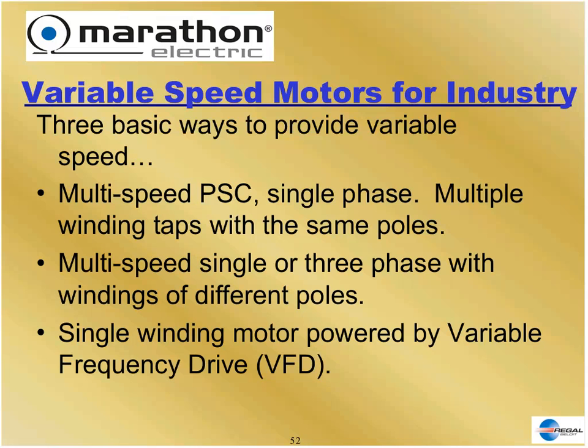Well, the three things, if you remember back on the slides, there's three things that determine the speed of the motor. There's the frequency, the number of poles, and the amount of slip. That's the only three things. If you have a motor that has a certain amount of poles and a certain amount of slip, and the utility supplies the frequency, you're only going to have a one-speed motor.